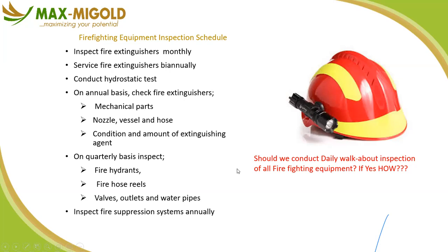No, if an extinguisher is expelled, if it's used, whether accidentally or intentionally, you need to get it serviced as soon as you can. On an annual basis, these guys will be checking for the components of the extinguishers. On a quarterly basis, we recommend you bring these guys in to check your hose reel, your hydrants, the valve, everything, just to make sure that there is water on the line. Some people do that just twice a year as against quarterly, because of cost, obviously.